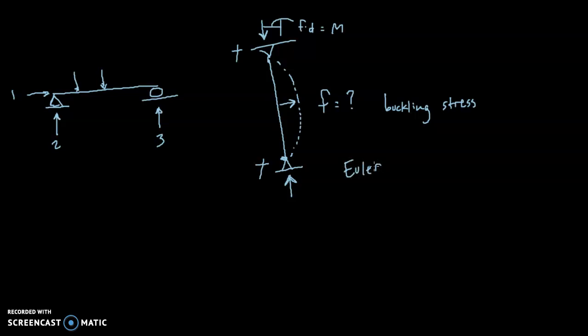He was among the first to come up with an equation to find how much stress or how much load. So we've got a load applied to our column, which when it's spread out over the cross-sectional area of the column causes stress. How much stress causes a column to buckle? So he came up with Euler's buckling stress, or load, depending on whether or not you divide it by area.